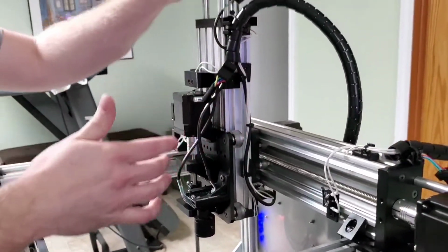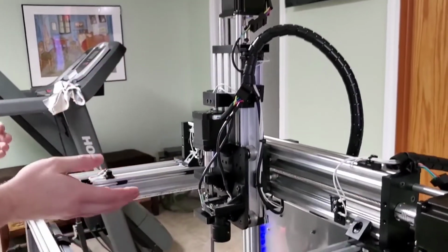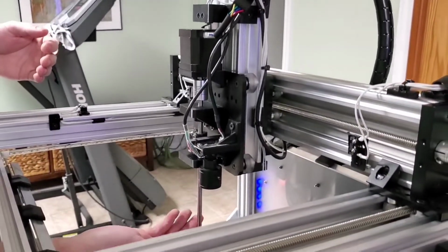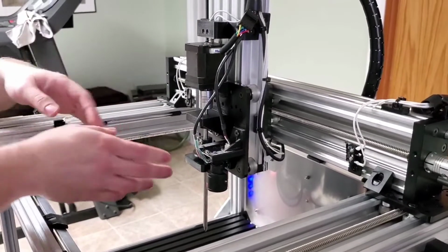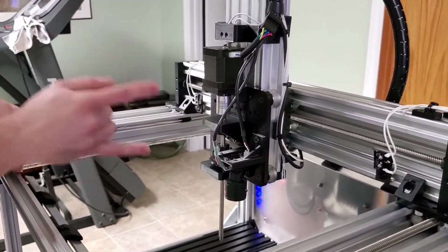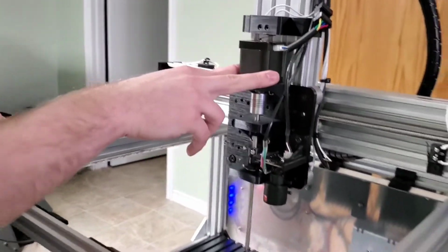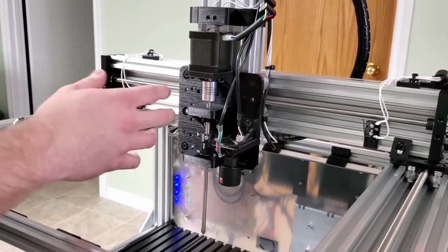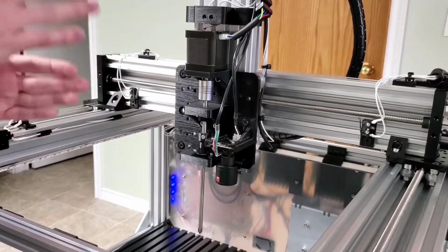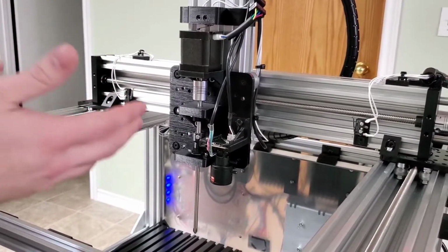This motor gives us the ability to move up and down. So when we actually meet the screwdriver, we're going to make contact with the screw and we're going to push it up and engage that limit switch. Now there's a few key brackets here. We have basically two shafts happening. So we have the motor shaft of the NEMA 17. This goes into a flexible coupler. The flexible coupler gives that ability so misalignments are solved instantly, or at least relatively well.